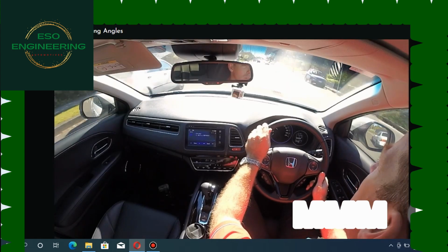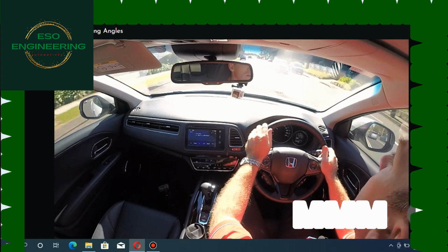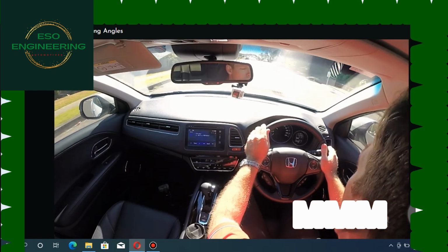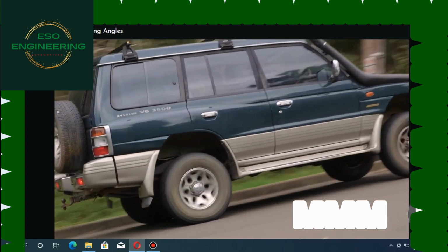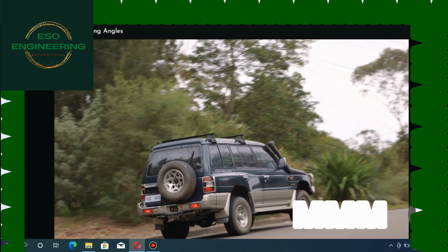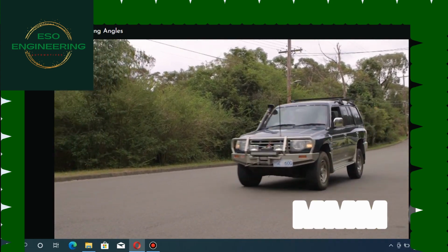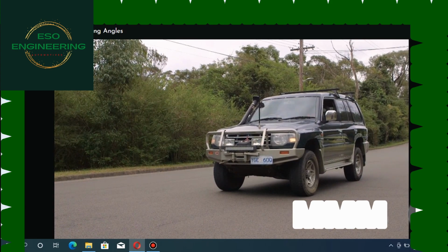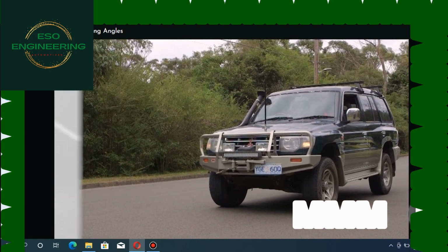Toe is affected by the forces resulting from acceleration and deceleration in respect to the road surface friction. As a vehicle accelerates, the front suspension will lift, the camber angle will change, and the toe will alter. Likewise, these forces will act differently under deceleration or braking, and will affect dissimilar driveline configured vehicles in different ways.